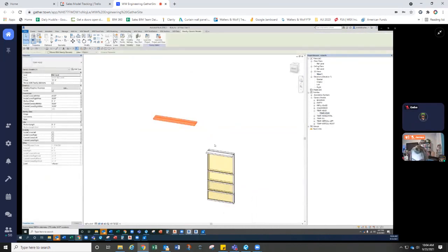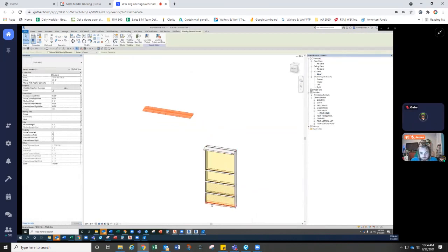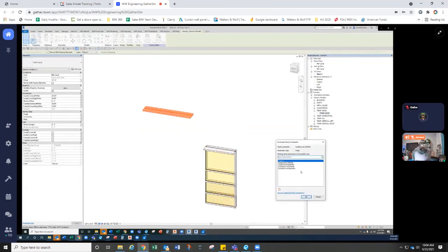But then once you tie it to the parameters that are unique to this frame, like the inside corner left miter, you'll see that it gets locked. So you don't have to change every inside corner right miter on each mullion. Instead, you just tie it to the master parameter within this family here.